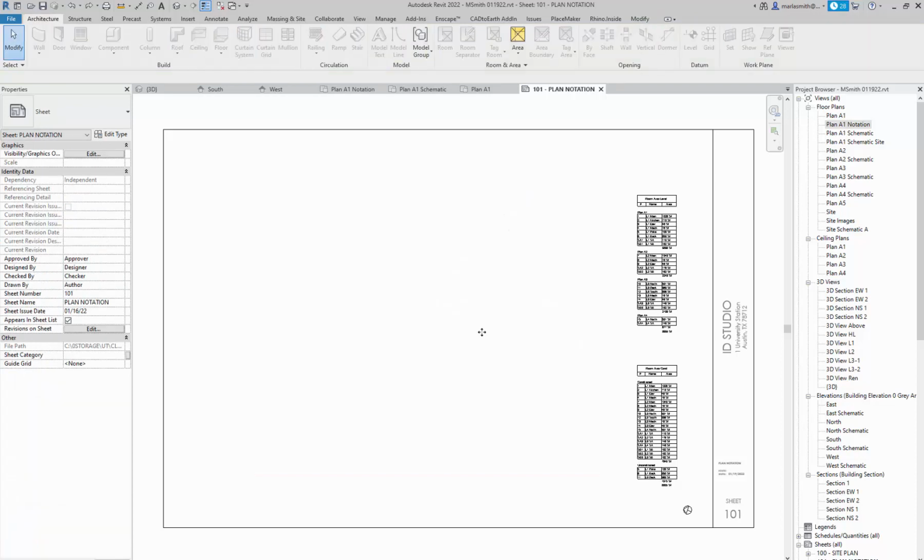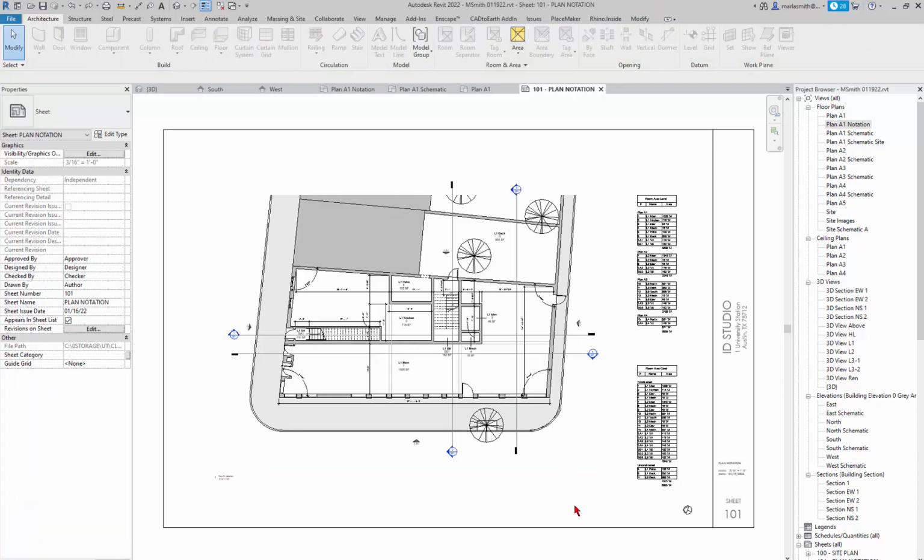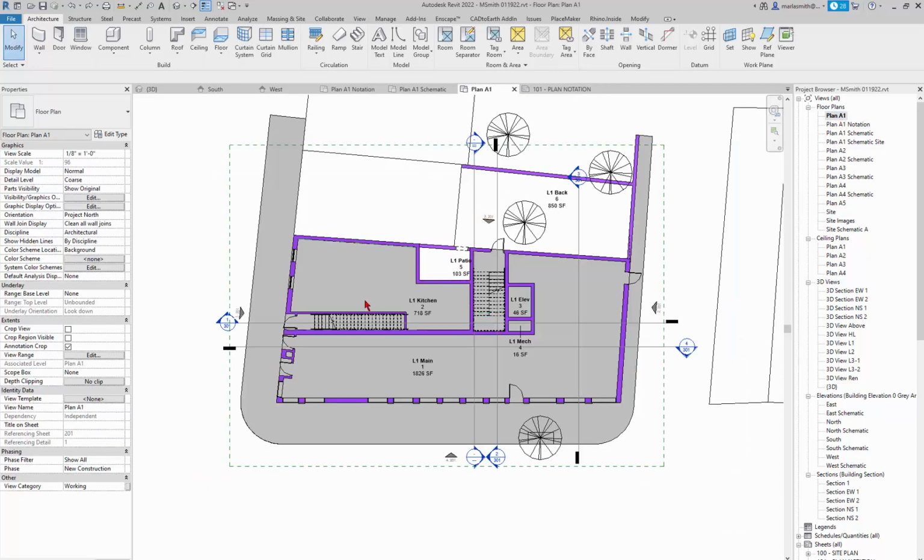So the idea with Revit is that you can have all these different settings and work in a very messy plan and change things that you want to change, and they will also update on the other plans because it's all the same model, just set to different visibility settings. So that's pretty much the way this guy is set up. In the next video, I will show you how to create your own floor plan and set some of the visibility parameters.